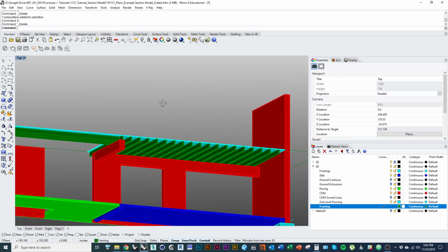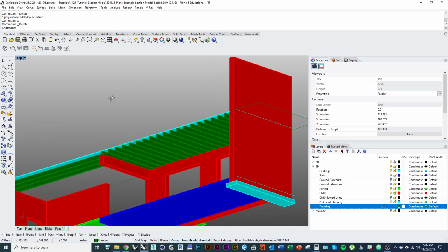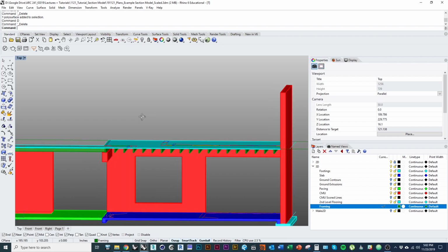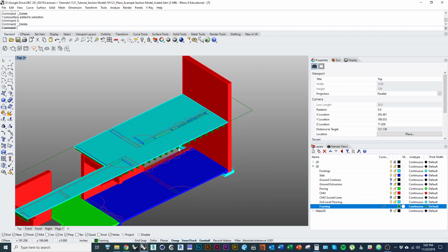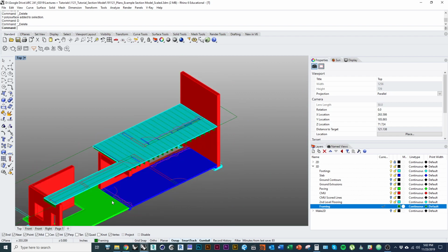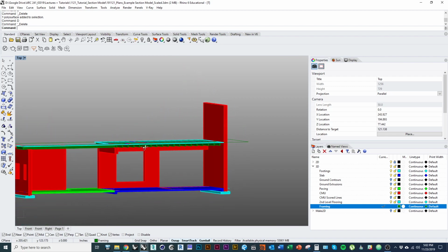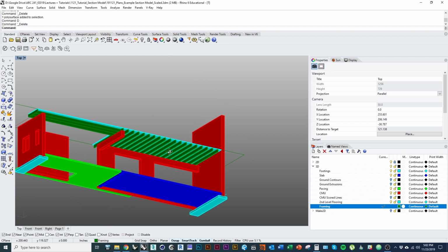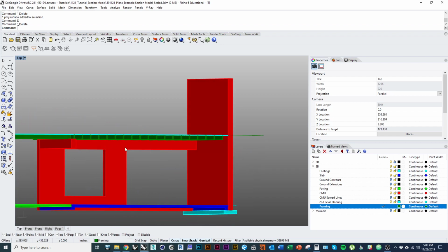Now, as you can see with this model, because of the way we cut through in section, we're going to have to model this surface as something with a certain thickness, and then glue the framing to it, and so on and so forth, as well as skin it. On the inside, obviously we would probably have at least a layer of cladding on the other side of the wood framing, if not an actual drop ceiling for mechanical systems and stuff like that.